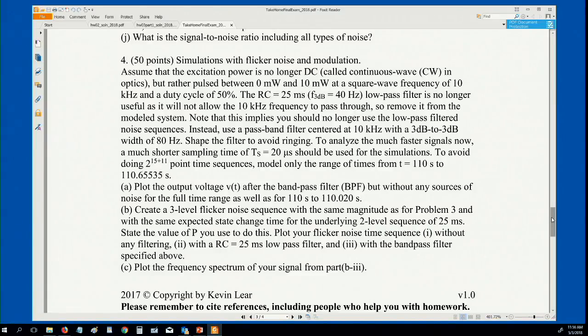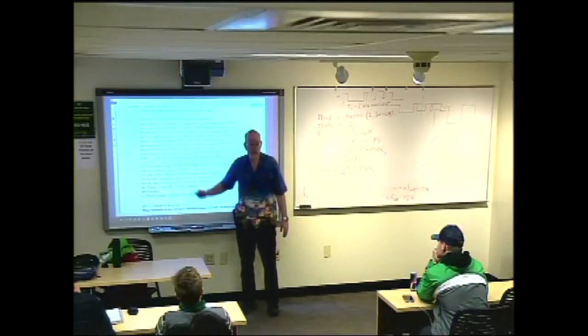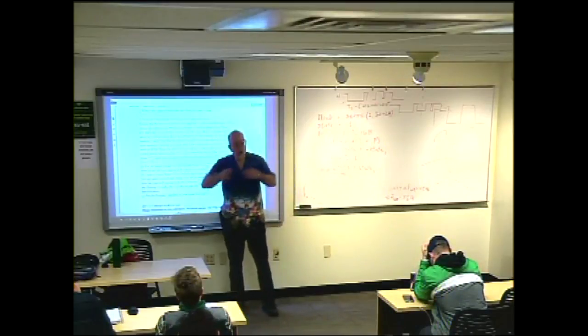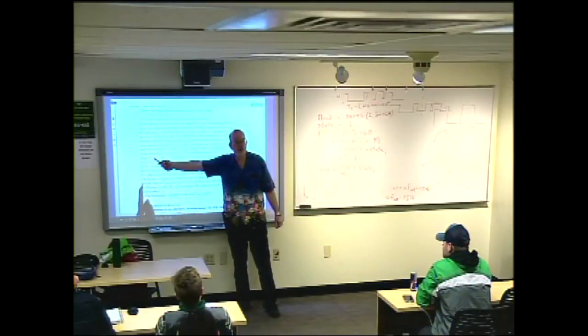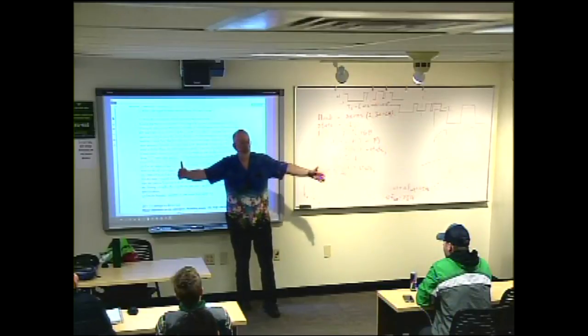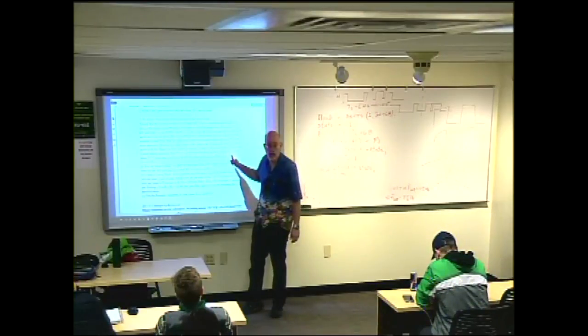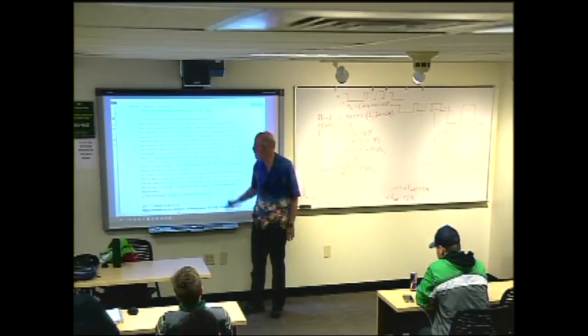Now that we have signals going much faster, we can't live with a 5 millisecond sampling time anymore, or else we're going to completely miss these transitions. So you have to greatly decrease the sampling time to 20 microseconds. Now, if I kept the same total time duration, you'd have 2 to the 15 plus 11, 2 to the 26 points in your vector. Let's not do that, okay? So instead, we're going to focus in and look at a very short, about a half-second window to analyze it. So we're just looking at that short time frame.